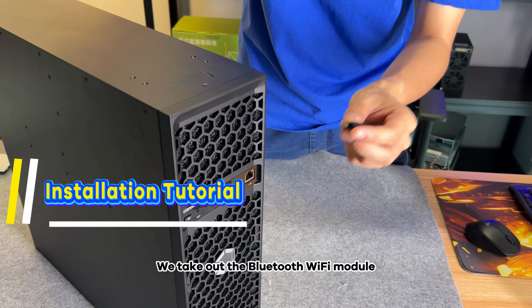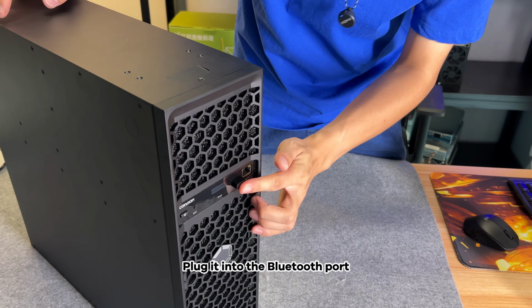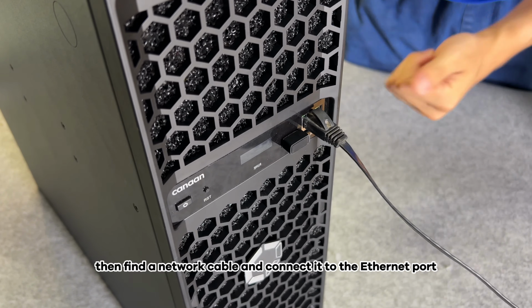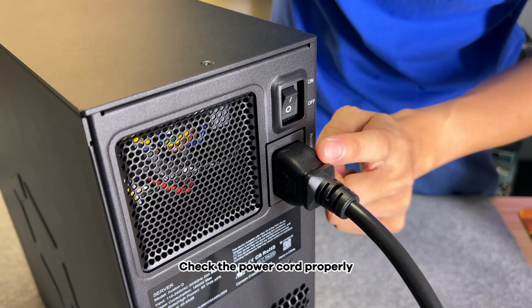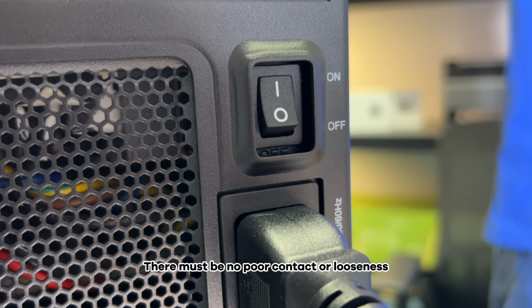We take out the Bluetooth Wi-Fi module and plug it into the Bluetooth port. If you want to use Ethernet, then find a network cable and connect it to the Ethernet port. Then we connect the power cord. Must remember to plug it in securely. Check the power cord properly. There must be no poor contact or looseness.